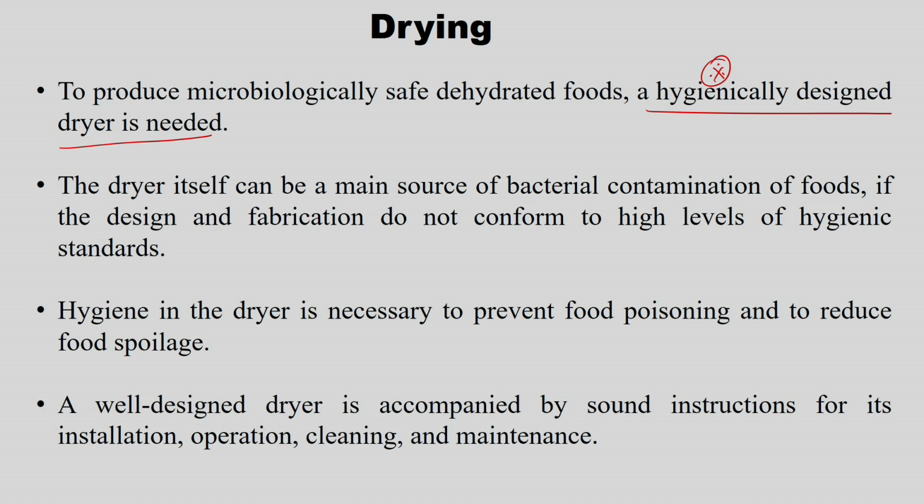The dryer itself can be a main source of bacterial contamination of foods if the design and fabrication do not conform to high levels of hygienic standards. So while designing and fabricating itself we need to take care, because wherever bacterial contamination occurs, we have seen in pasteurization as well as sterilization, the holding tube, why it should be at some slope, and also the walls and places where milk chunks may stay, so that should be cleaned properly, right.